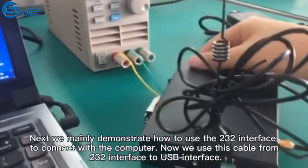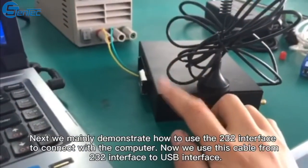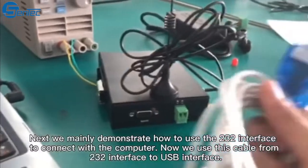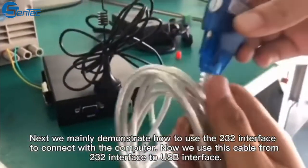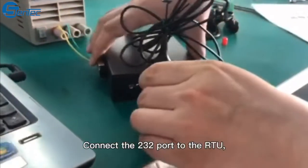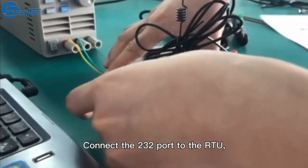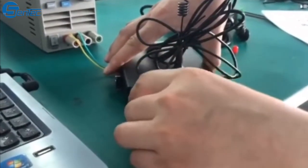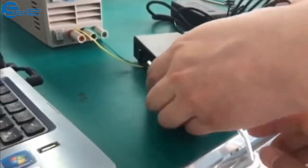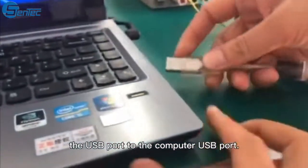Next, we mainly demonstrate how to use the 232 interface to connect with the computer. Now we use this cable from 232 interface to USB interface. Connect the 232 port to the RTU, and the USB port to the computer USB port.